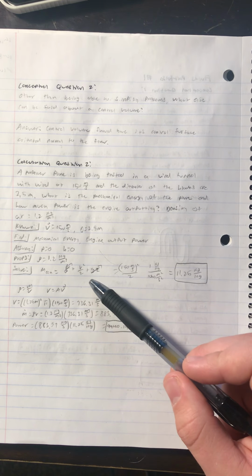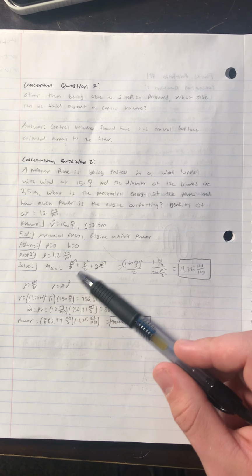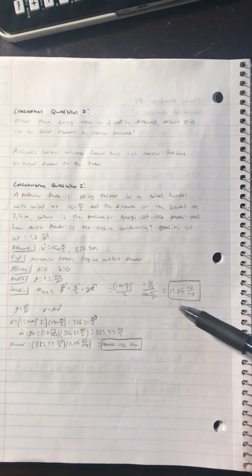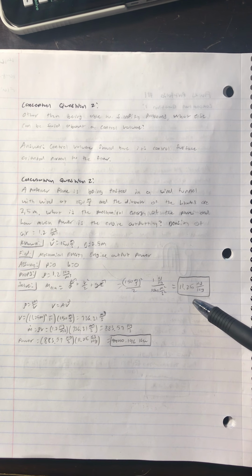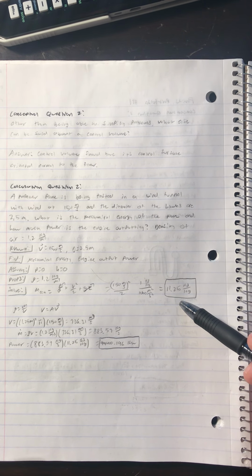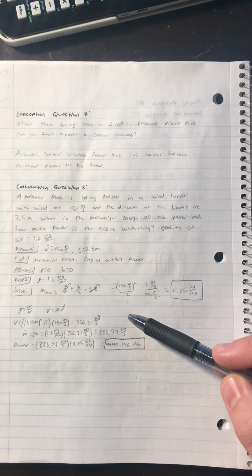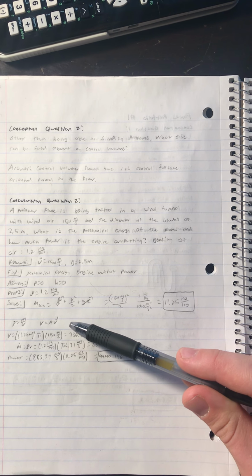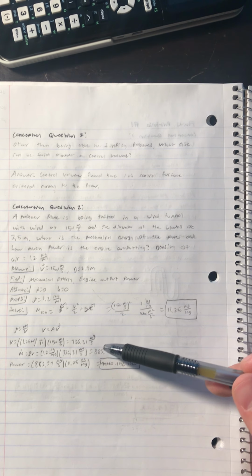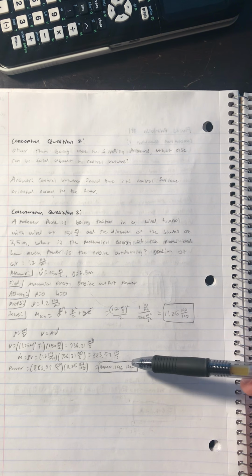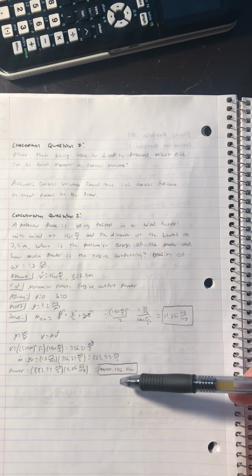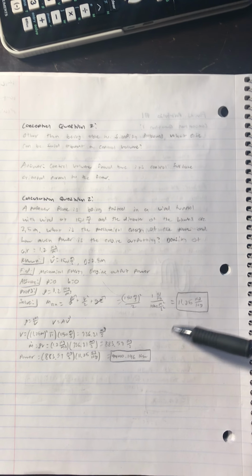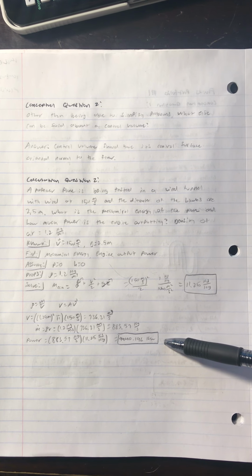To solve it, we go to our Bernoulli's, and we're able to just knock out the pressure and the height terms, and then solve for mechanical energy, which turned out to be 11.25 kilojoules per kilogram. Then we have to solve for the power output. So we use our rho equals m over v and our V dot equals A v equations. We get a volumetric flow rate, and we get a mass flow rate from that, and then we're able to use the mass flow rate times this mechanical energy output, and that is able to give us an answer in kilowatts.